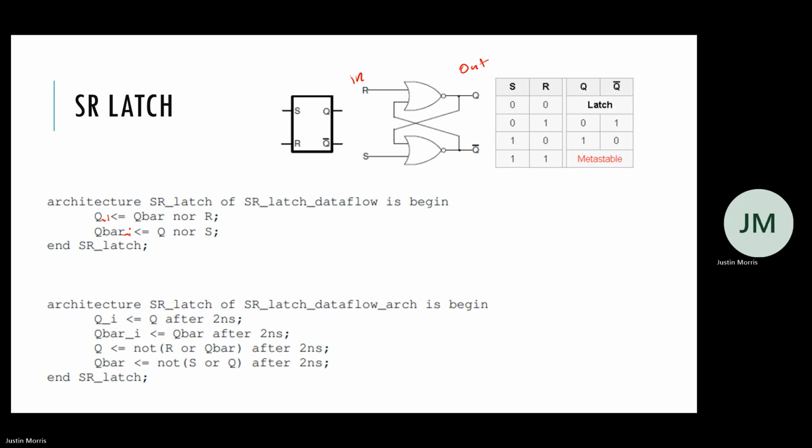And then because they are internal, we would then be able to read from them, right? But now we need to still make sure that our output is connected. So we just connect the outputs to the internal bits. Okay. So Q bar, like that. So now we can read from what we want as outputs without VHDL complaining.